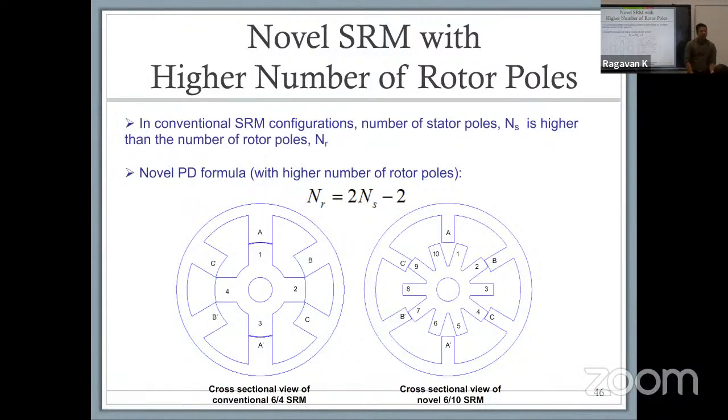So one of the key advantages, like I said before even, is that when you increase the number of teeth on the rotor, the first thing is you end up lowering your torque ripple. What we normally would have seen for an AC machine, you would have increased the number of phases. That gives you better torque performance. Increase the number of poles, gives you better torque performance. The same way, increase the number of teeth and it gives you much better average torque performance.